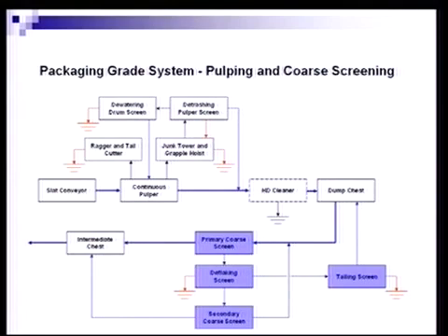Of course, the screening loops aren't just standalone screens by themselves. They are always multi-stage affairs where we'll arrange the screens such that the fiber is recovered in the subsequent stages and the debris is removed ultimately from the tail end of the system. In this graphic you'll see a three-stage coarse screening system.